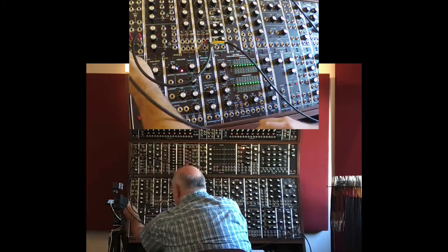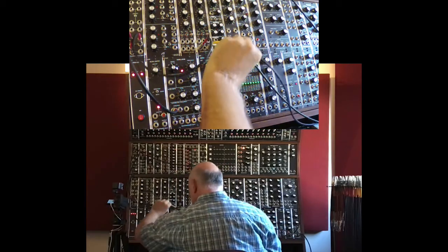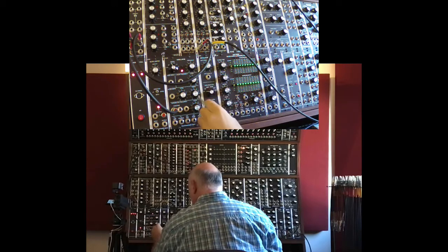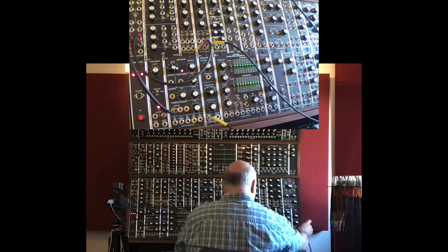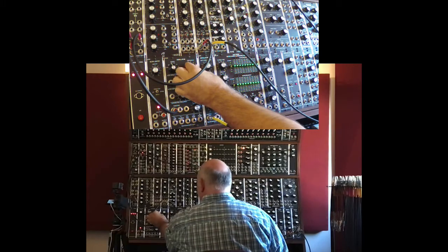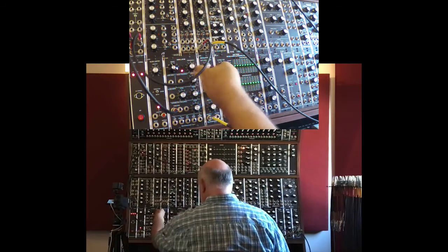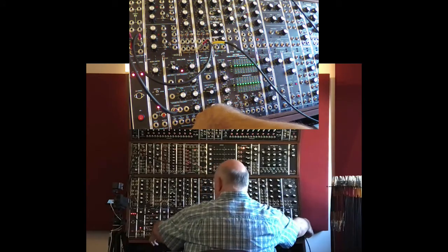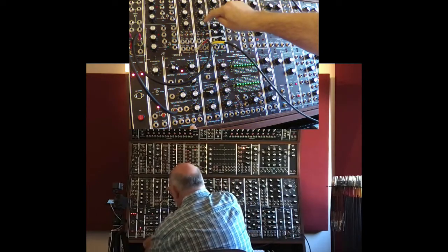So, if you haven't already, take your pitch CV into 1 volt per octave. I'm going to use a 4-foot cable because I'm going to go straight to the VCA, the final output VCA. Positive output all the way up, sine wave. Plug into signal input 2 in the VCA and tune. The other thing you can do is hit mute on the Mackie, put it into DP audio track, put in a tuner, and tune it. They need to be really close. Now they are. I unplugged the 4-foot cable, so now the modulator is tuned pretty close to the carrier.